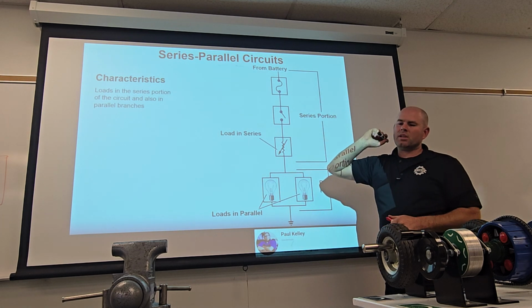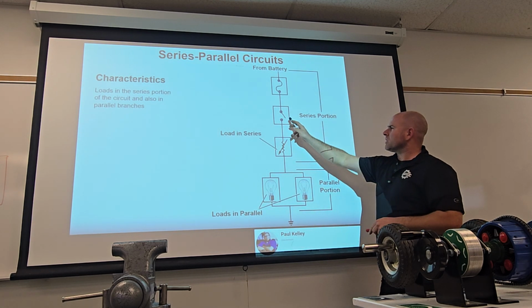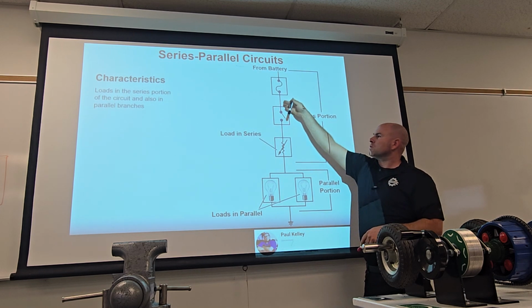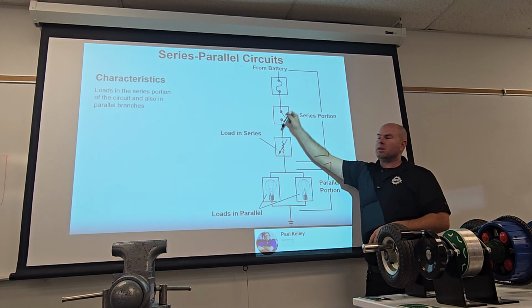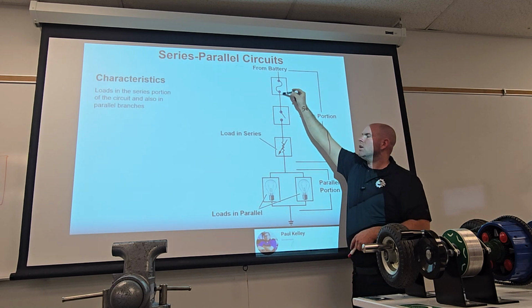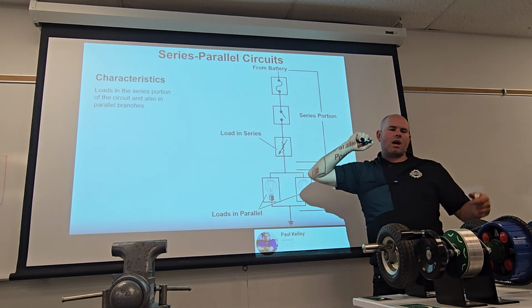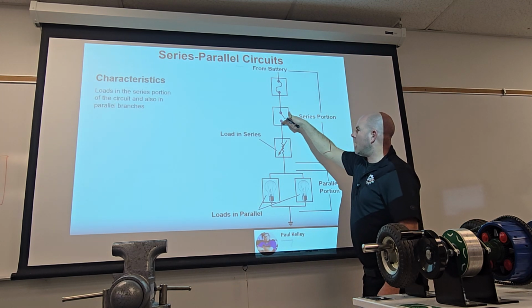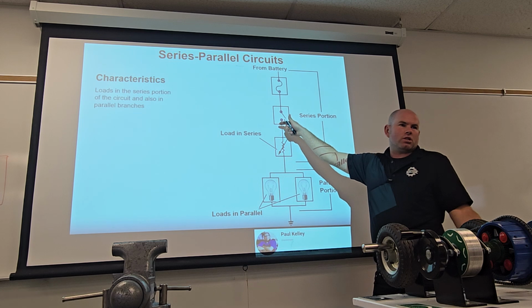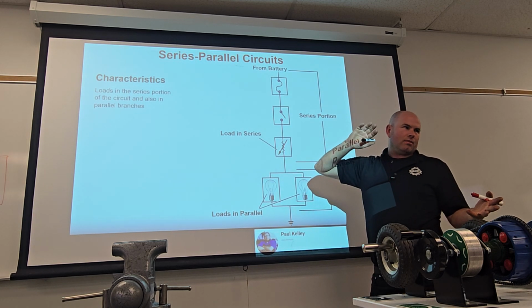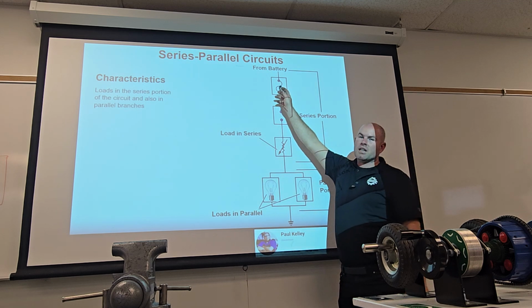So with a jumper lead, it's helpful. Like, for example, if we had 12 volts, 0 volts, and the switch was closed, do you know what's wrong? 12, 0, 0, 0, 0, 0, 0, 0, 12, 12. The switch is no good. But let's just say I want to double check myself. I could use a jumper and I could hook here and bypass the switch. That's what a jumper does. And that's part of the reason I'll sometimes use an unfused jumper, is because it's already got a fuse.